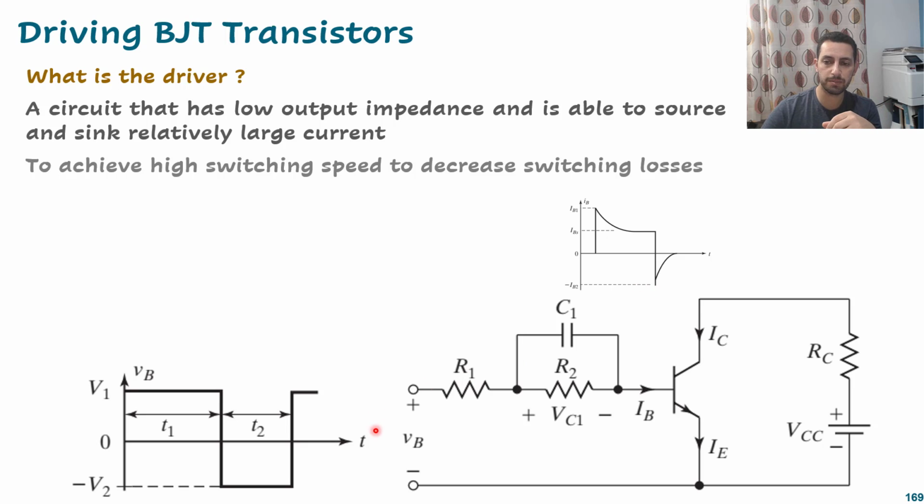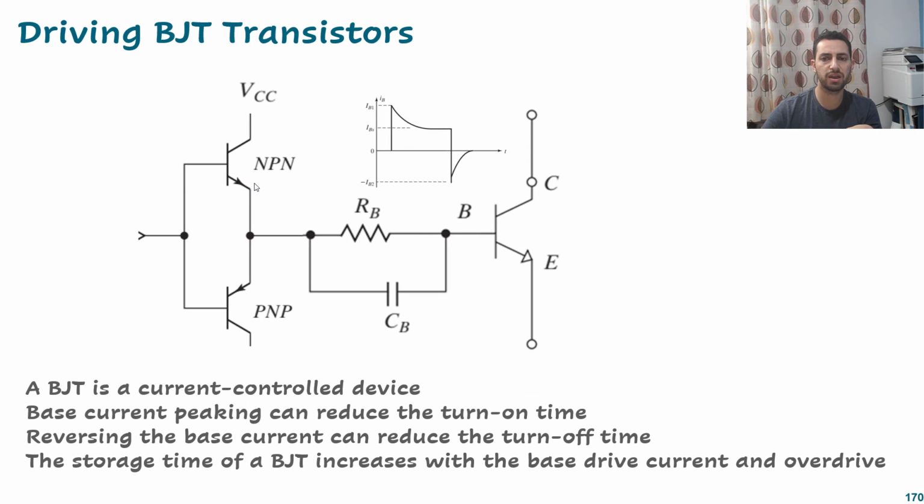Now we can supply the positive and negative voltage by another circuit, which looks like this one, okay? This one is called the totem configuration. And when we supply here positive 5 or 0, okay, 5 and 0, the 5 volts will turn on that transistor and makes positive voltage go to that point here, and also pushes a spike of current to the base, okay, this one.